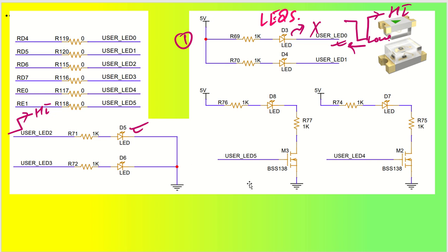Let us say you want to learn a lot of things using microcontroller IO. Instead of directly handling the LEDs through microcontroller IOs, you can send it through the MOSFET as well. Once you make it high, this MOSFET will start working, and this is how the LED will start glowing, because it will take the complete path. Once it goes high, this MOSFET will get switched on. And you can change your resistor value based on your convenience, like how much current you need to drive these particular LEDs. This configuration is actually utilized for understanding purposes, like how to control the MOSFET.